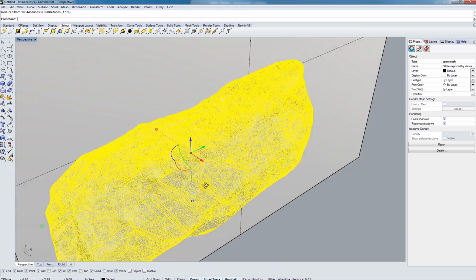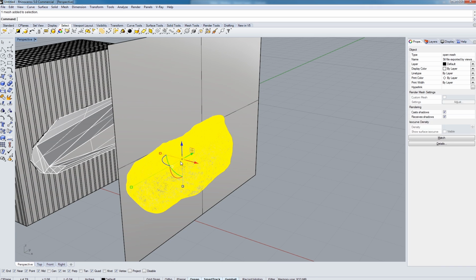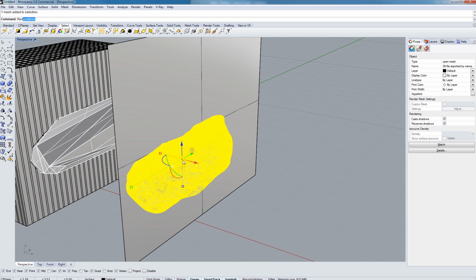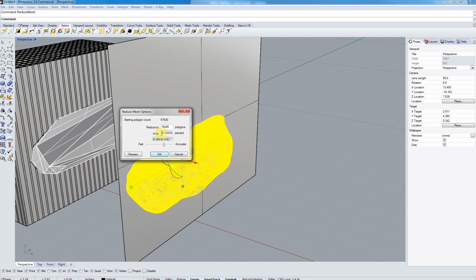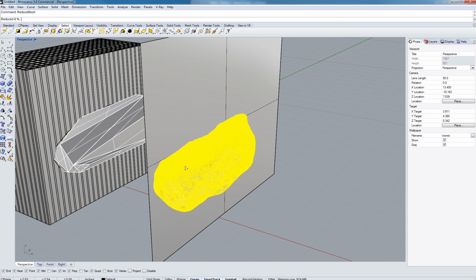All right, once that's all finished up, you can see that your mesh slightly modified itself a little teeny bit. One other tactic I typically do if you do the mesh reduce is unclick this box, and I typically just take it down by a percentage. Start off with 25, and this should run relatively quick. Basically this will allow Rhino to split this mesh without any issues.